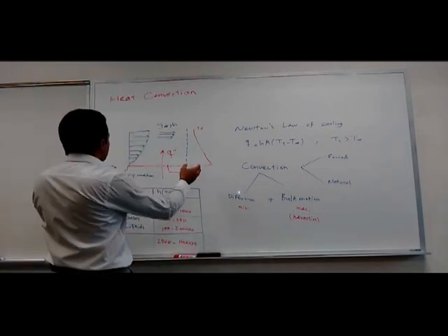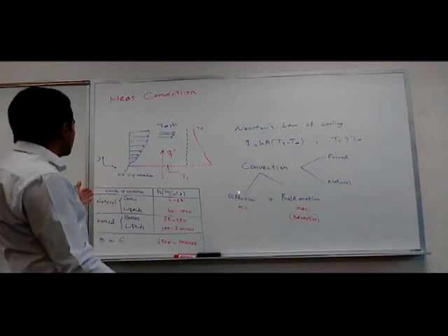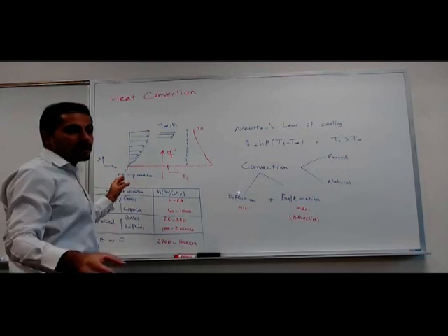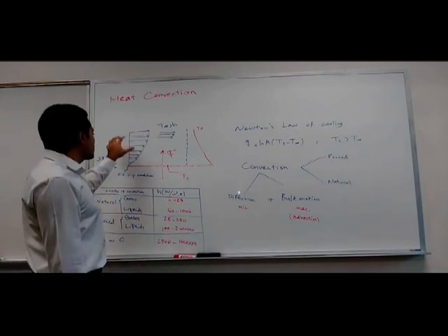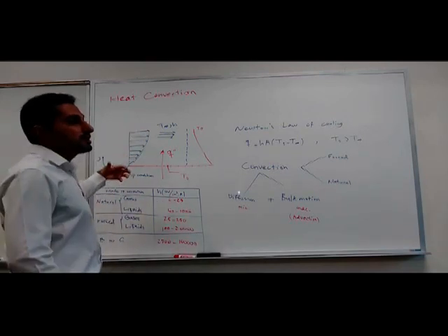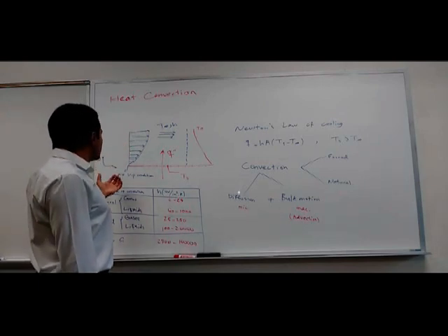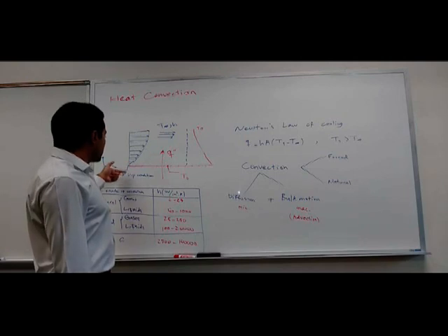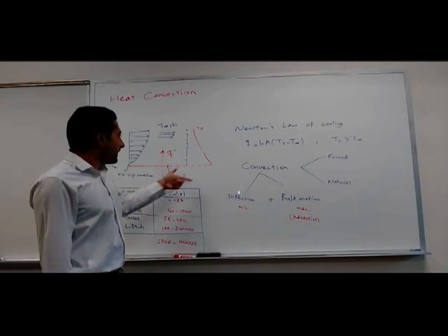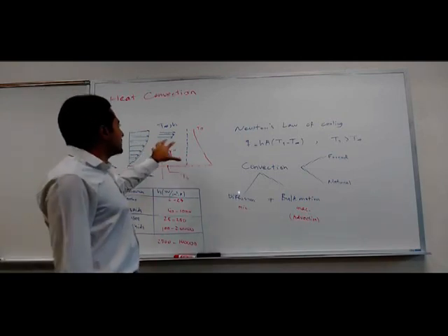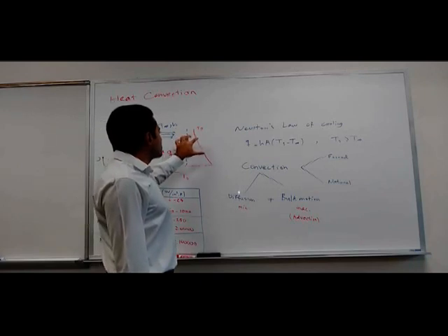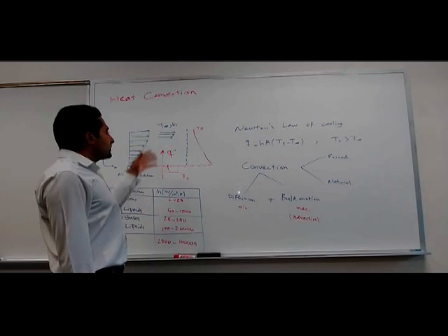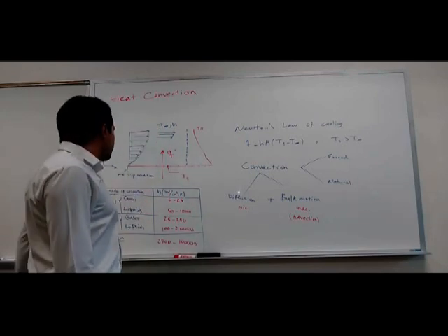You can see in this picture that we would have a hydrodynamic or velocity boundary layer because of the velocity change here, because of the no-slip condition at the surface of the plate. Similarly, we have a thermal boundary layer here if a temperature difference exists.